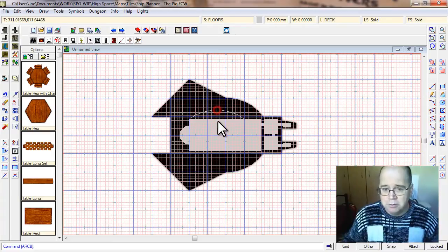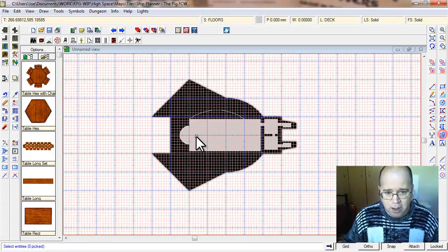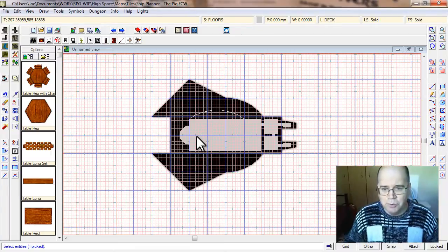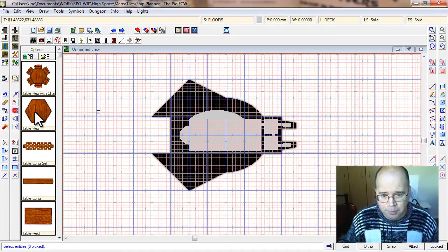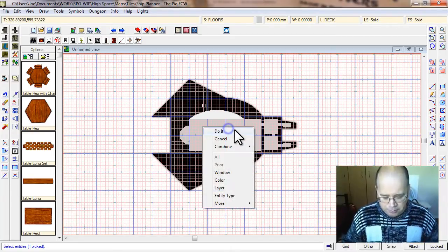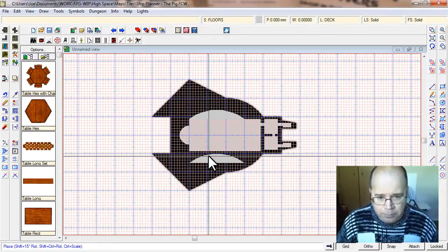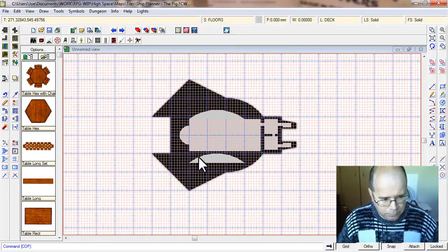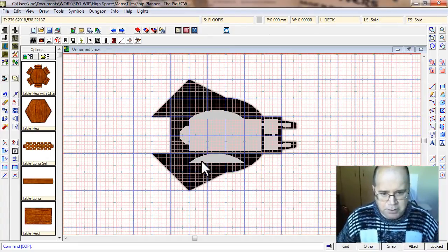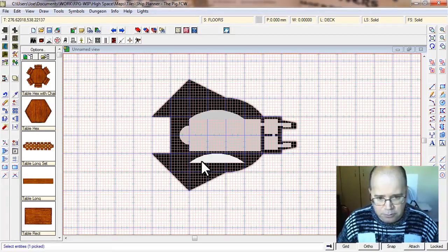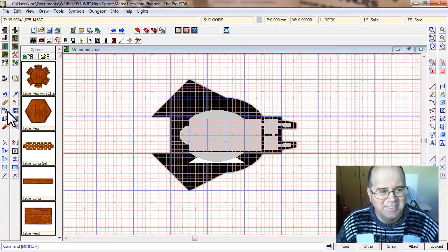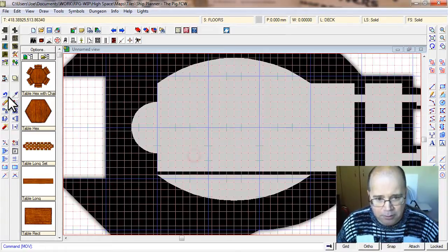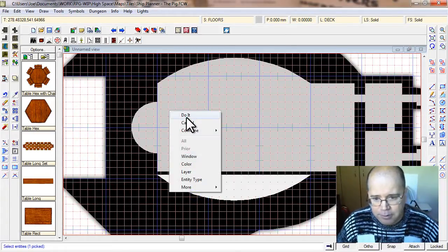And multi-poly, and here's a trick: if you multi-poly previous line that you've just drawn, go do it, it will align it for you already. And again, I'm going to copy that previous element, do it, bring it down, mirror, mirror the previous element, P for previous, do it, just draw your axis, and let's move that into space as well. Click on the move function, do it, done.